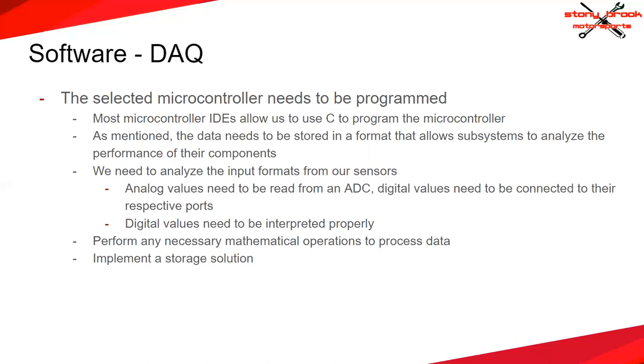the microcontroller. Analog voltages need their own analog to digital converters, and digital signals will need to be interpreted properly. In all, this is going to require us to read a lot of monotonous data sheets, but it's imperative that we pay close attention and interface these components properly. Otherwise, our data will just be garbage. The data will then need to be processed, likely into ASCII text, so it can be stored in its file.